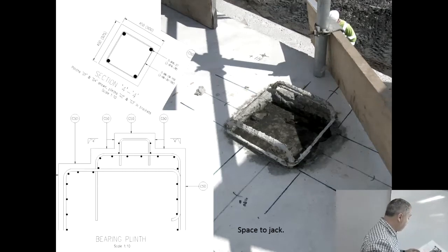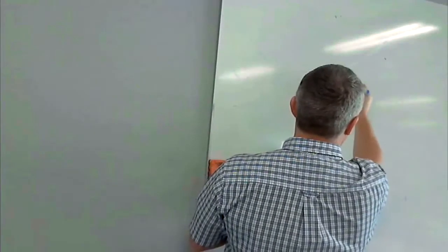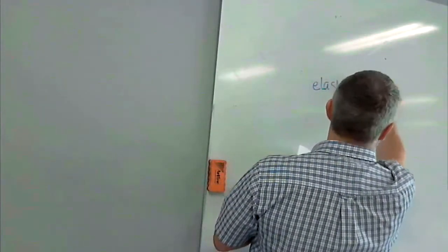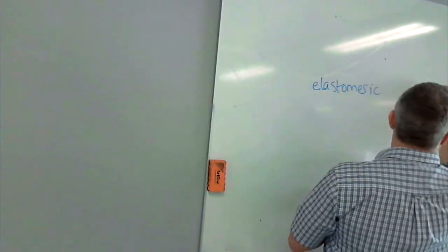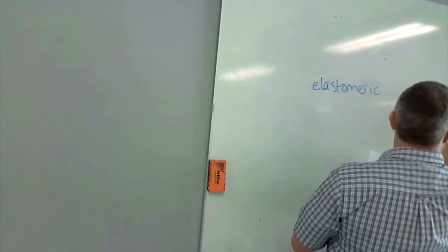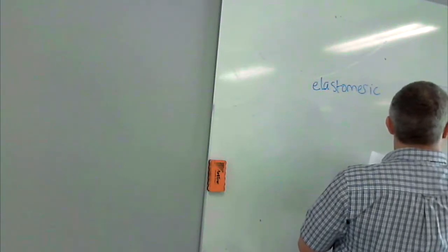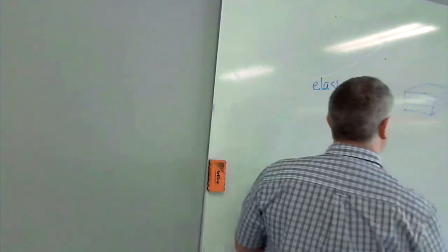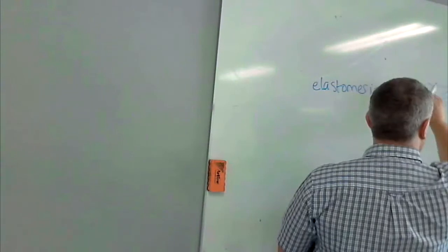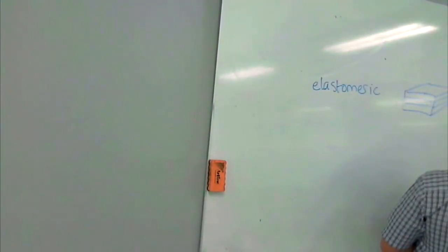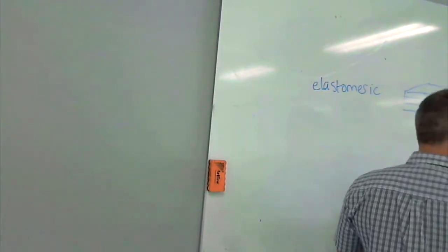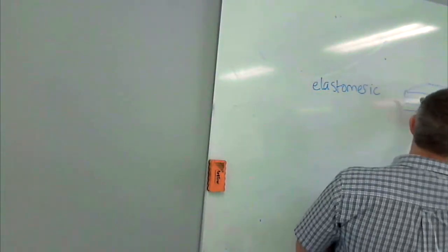I don't know if you have to specify this for fill areas, but yeah, so you've got the elastomeric bearings, and we've just got different layers of this rubber material that when the bridge is moving in terms of moisture and thermal movements, it's just bending across.